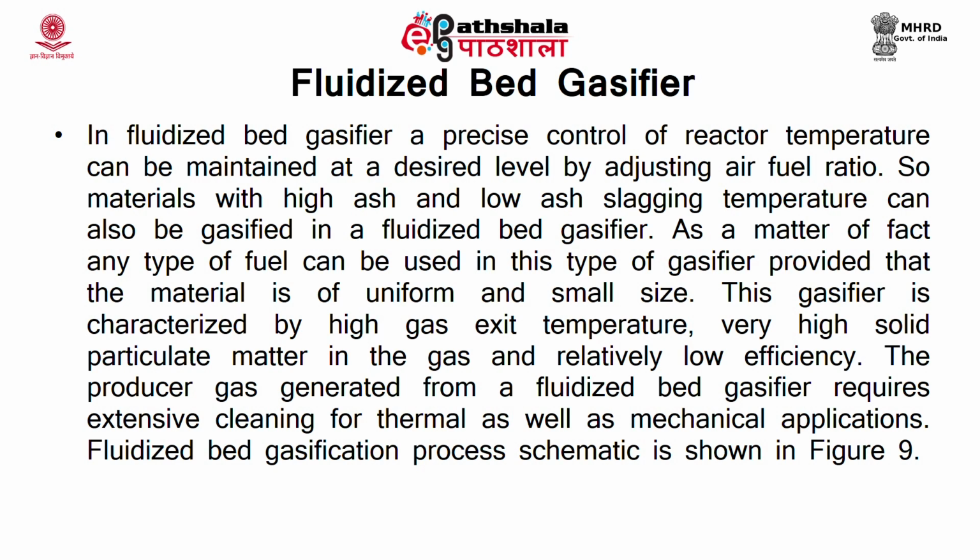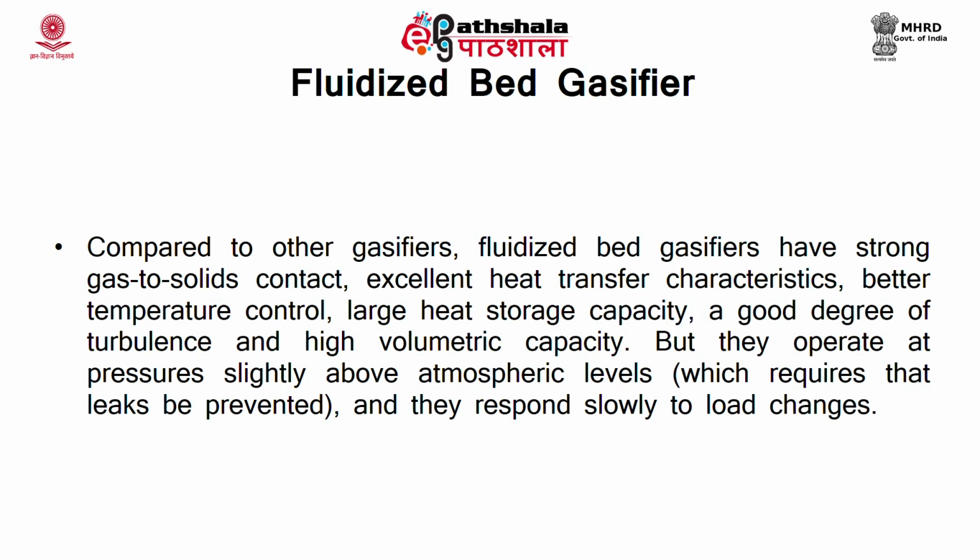But you should be very careful in using a uniform and small size material as a fuel in this type of gasifier. This is characterized by high gas exit temperature, very high solid particulate matter in the gas and relatively low efficiency. The producer gas generated from a fluidized bed gasifier requires extensive cleaning for thermal as well as mechanical application. So, it has strong gas to solids contact, excellent heat transfer characteristics, better temperature control, large heat storage capacity, a good degree of turbulence and high volumetric capacity.